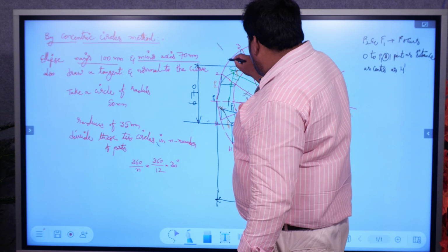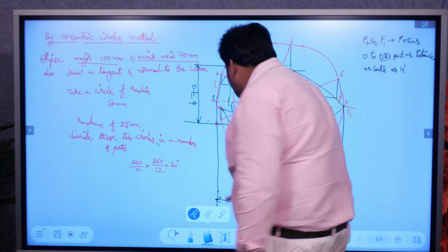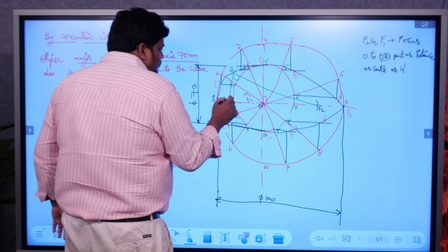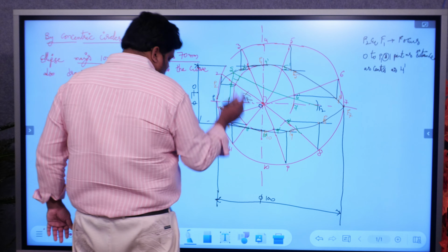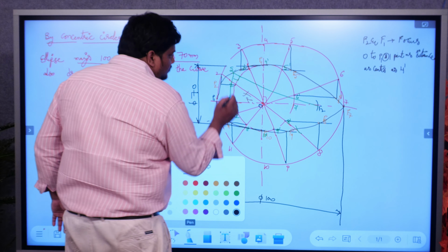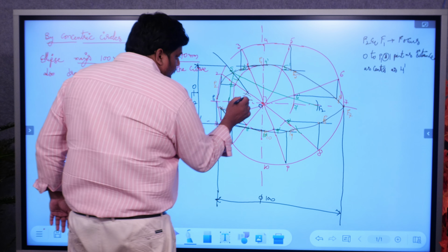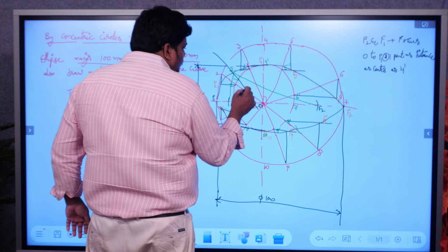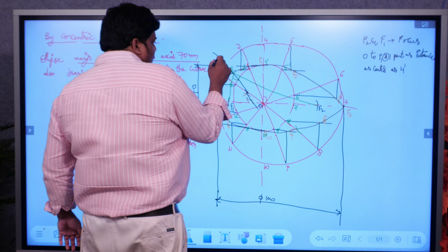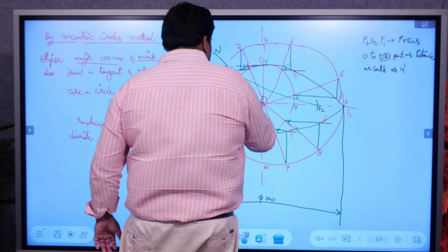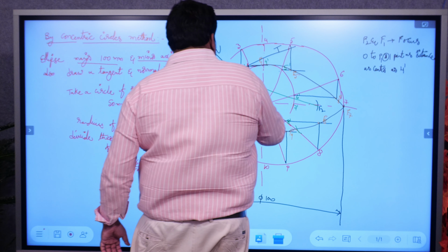From that point you need to draw one line. This point is S. From that point we need to draw one line passing through the previous cut section points of the arcs. This is called the normal line. To this normal, if you place the set square at 90 degrees, this is called the tangent line, tangent TT.